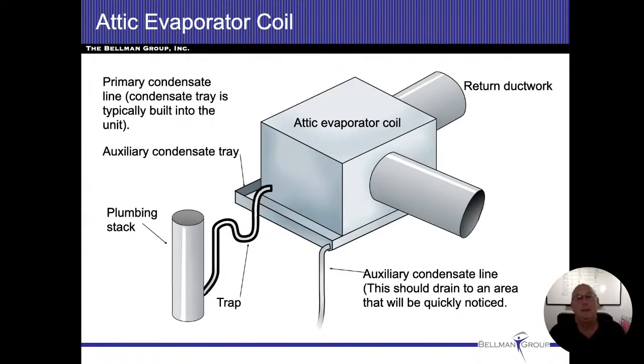All right. Now, if we're on the first floor or an attic install, we need to have a secondary means to protect against any sort of overflows or clogs that come into play. So if we're in an attic or anything other than a basement concrete floor, let's put it that way. So if I've got structure underneath us, we need to have some sort of protection. Even with a crawl space, you have to do that too.